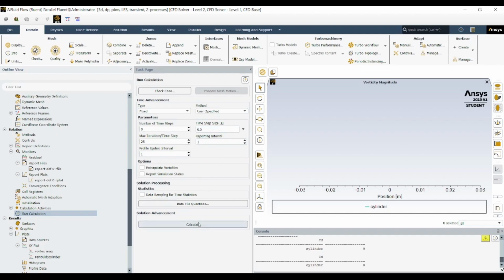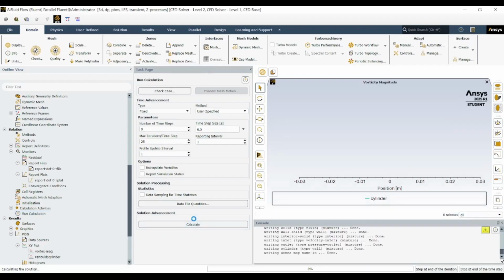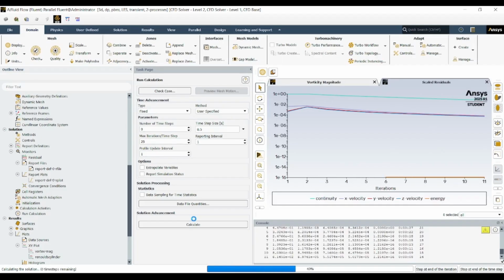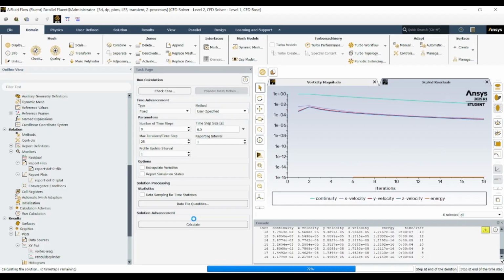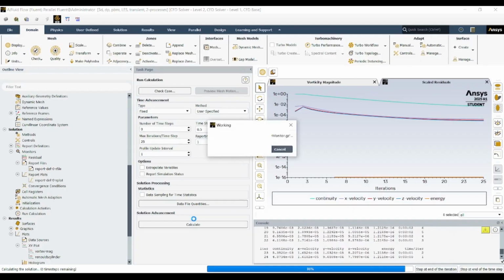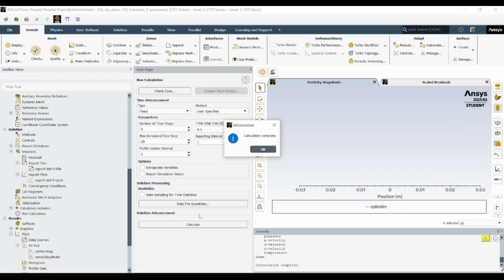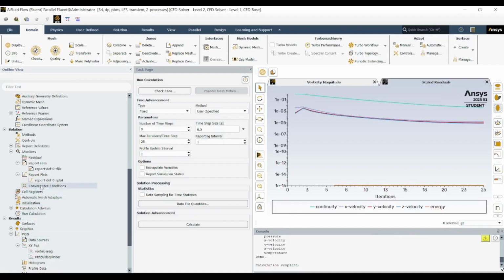To further interpret flow structure, plot Reynolds number-dependent parameters, like the drag coefficient versus Reynolds number, by running several simulations with different inlet velocities. This helps identify critical transitions in flow regimes: steady laminar flow at Re less than 40, onset of vortex shedding near Re approximately 47, periodic laminar vortices around Re equals 100 to 200, and turbulent wake beyond Re equals 1000.